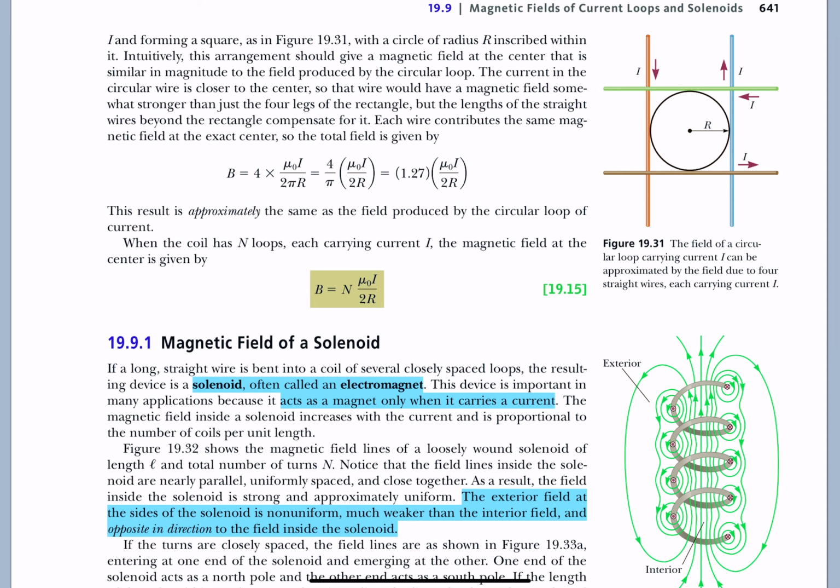That's why we like to use very, very thin wires so we can pack them really close together. Thick wires, especially because they have to be coated in insulation, push the wires farther away from each other, and it begins to weaken the overall effect of your electromagnet. But of course, if you have thin wires with very thin insulation and you try to have lots of current going through it, you end up heating up those wires substantially. And you might even get some of that current to penetrate the very thin insulation.